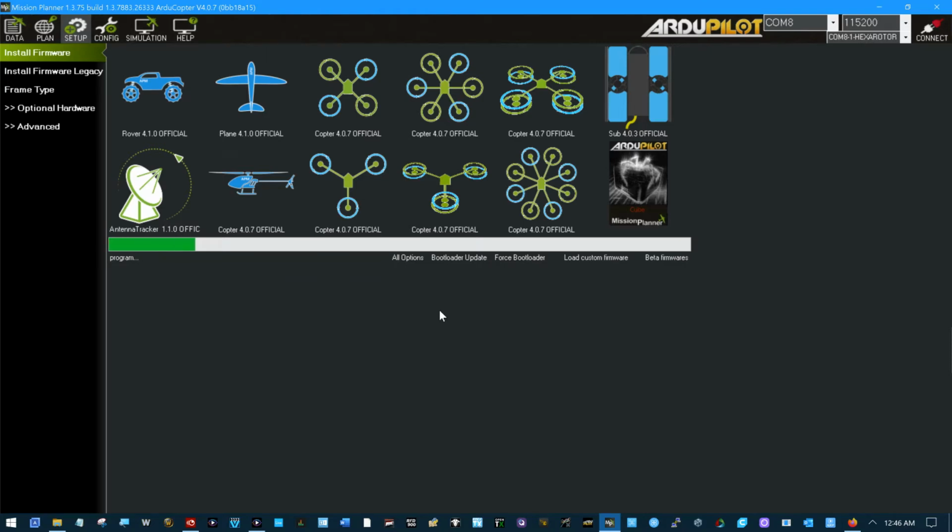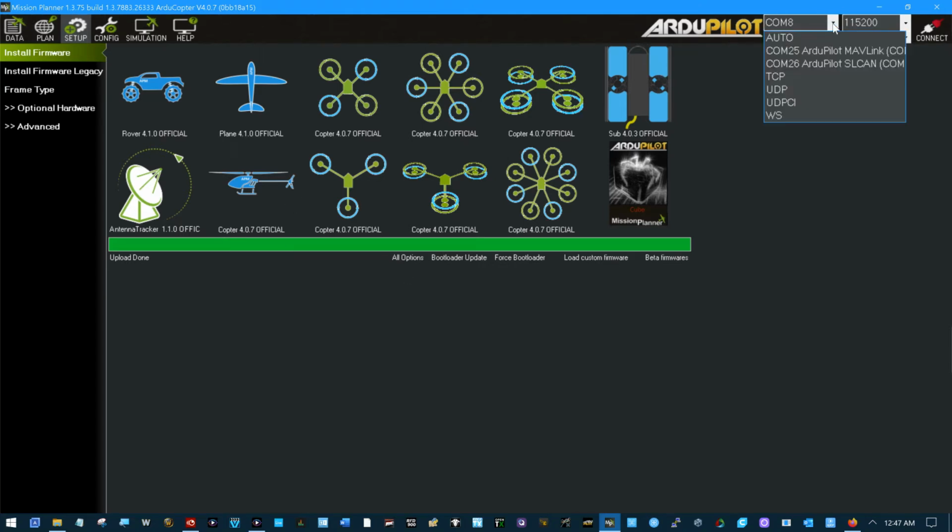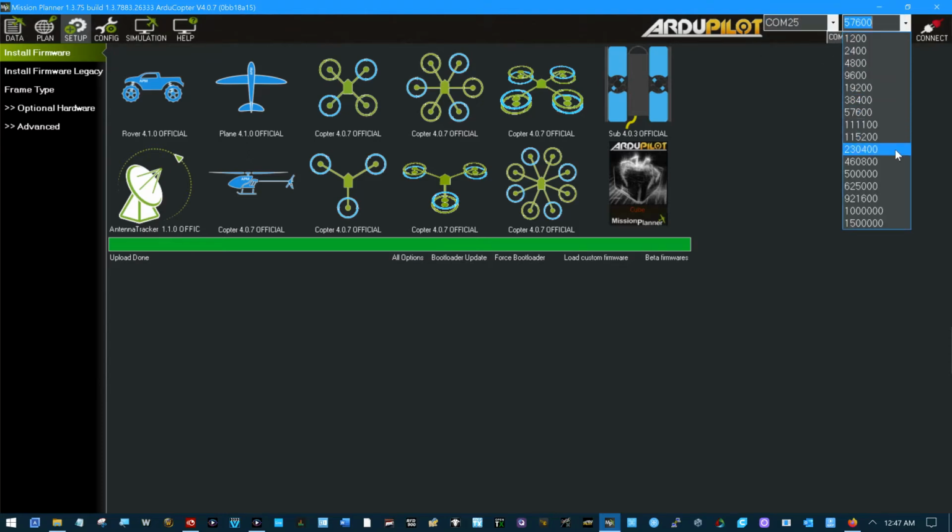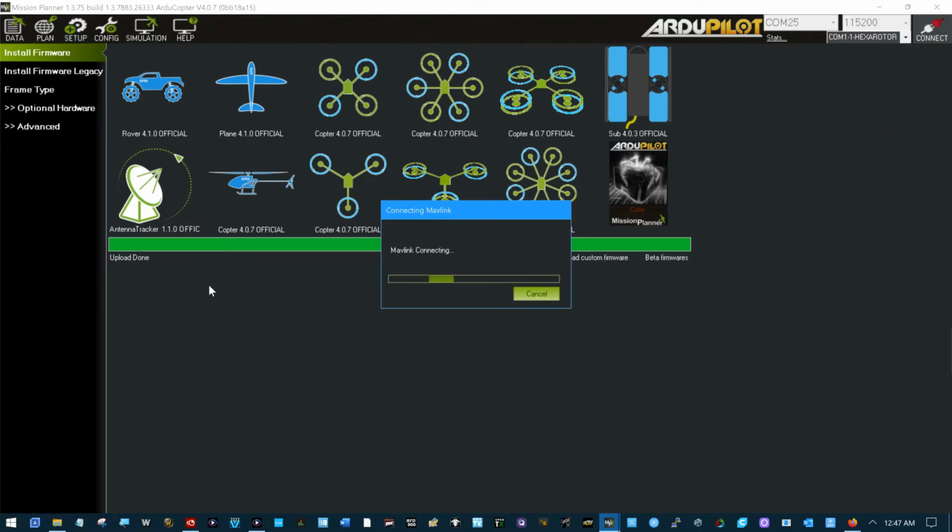You see, my old ESC, well, I didn't do it through the flight controller for the thrust. We will be doing that with the Sky Hunter. But I think those old ESCs just aren't up to date with this software, and it doesn't understand them, so it doesn't even let you have that drop down list to choose from. When you click Calibrate ESC, it just comes up with that error message. That's what was happening to me on the mini Talon.